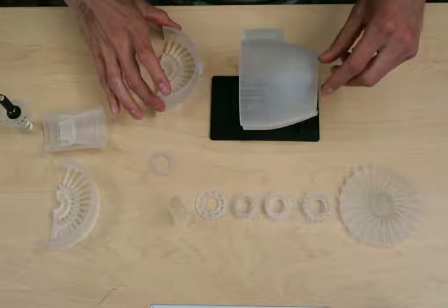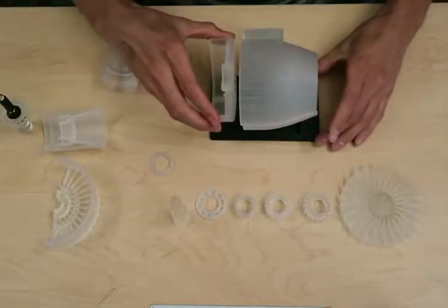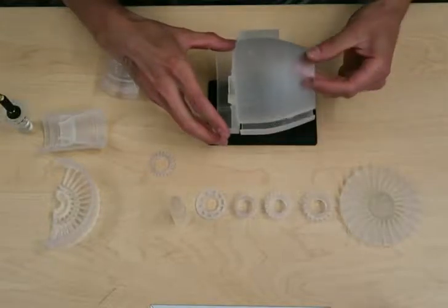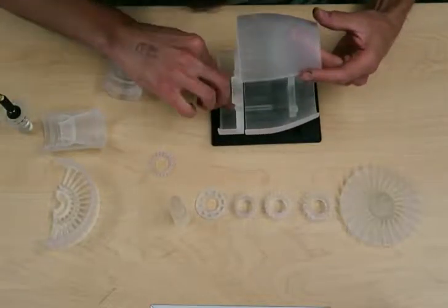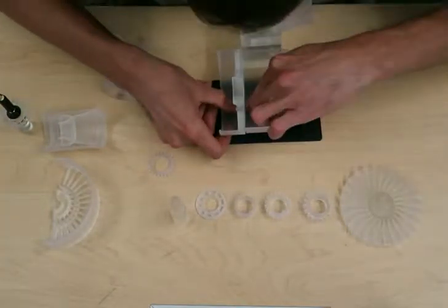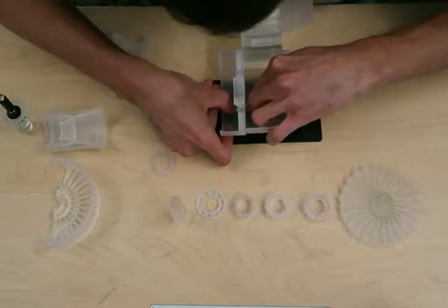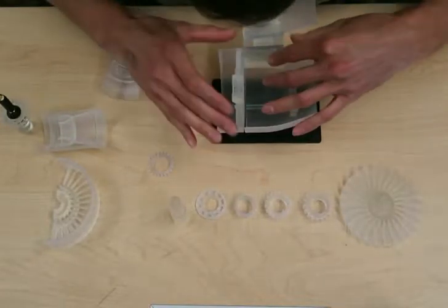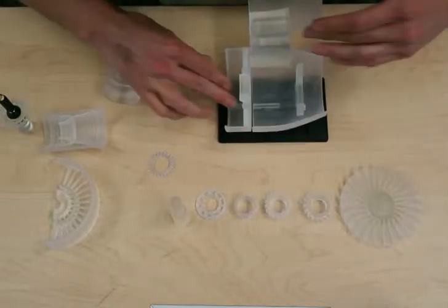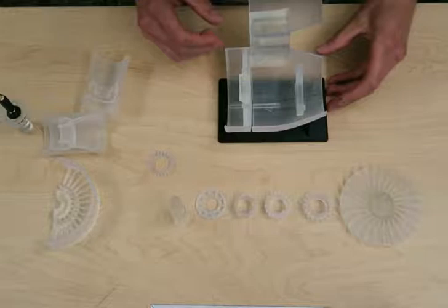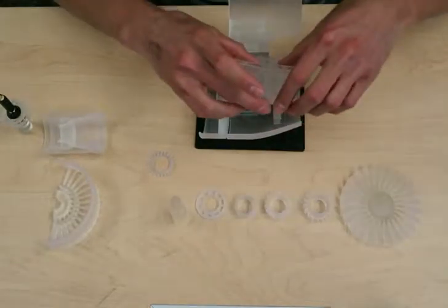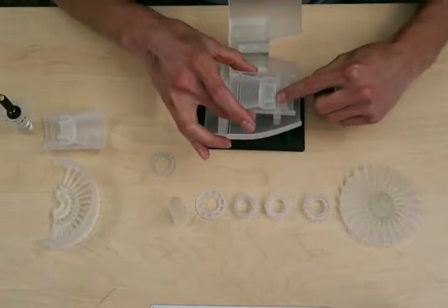So here, this is just a slip fit dry assembly of our 3D printed components comprising our engine. The nacelle and internal fan blades were printed using an SLA printer, and the base was printed using an extrusion printer. The reason why the blades and major engine components were printed using SLA is because of the precision and accuracy of prints that an SLA printer can produce.